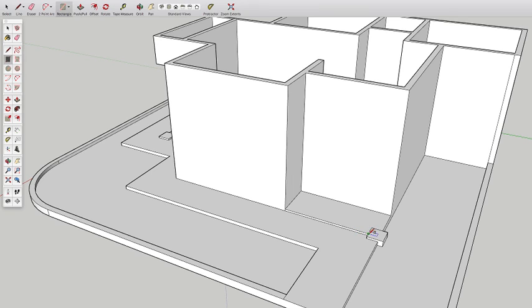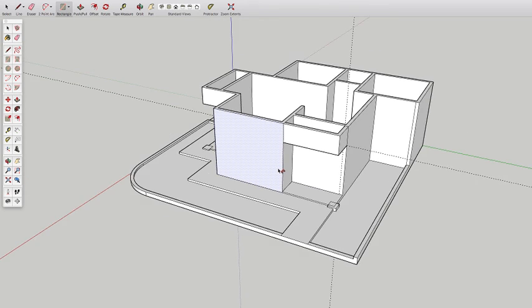Use the rectangle tool, just create the line around and then select it. All right, select, select, select, select, and like I did, 240 centimeter by 15, the guideline, and create a rectangle. And now use your follow me tool, and that's it. Boom, done.